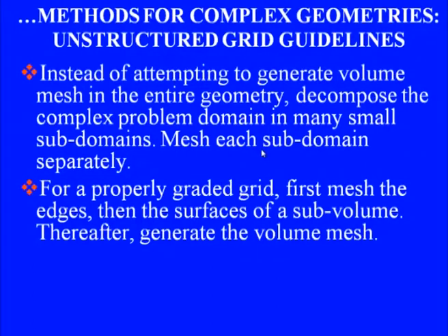Similarly, let us say we have, in compressible flow, the presence of shock waves; the grids should be finer in those areas. So you have to provide appropriate gradation of the grid. And one more aspect which we should take care of: there shouldn't be an abrupt jump in the mesh size. So the gradation again should be as smooth as possible to obtain accurate numerical results.